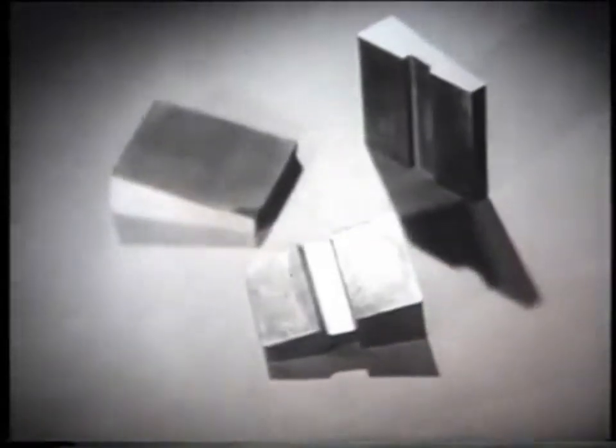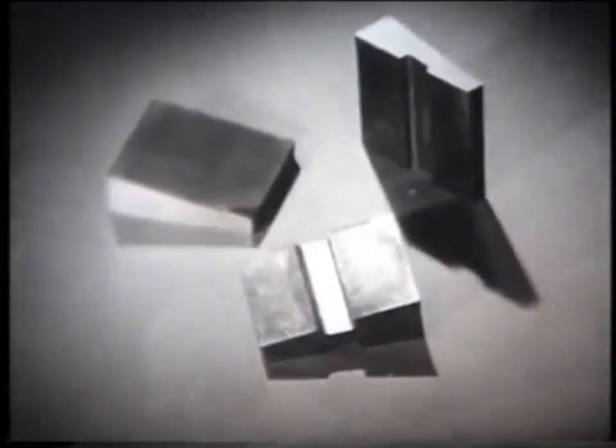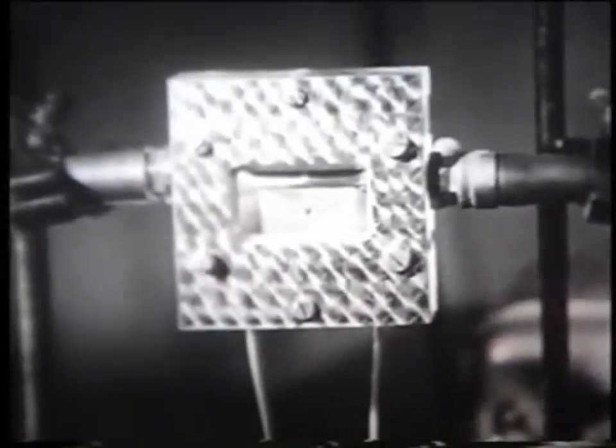These methods make it possible to achieve a metal removal capacity of 1,500, 1,800 cubic millimeters per minute per 1,000 amperes of operating current. The treated surface has a high purity class. Besides, there is no zone of thermal influence. A very important feature of electrochemical processing is that the dissolution rate does not depend on the mechanical properties of the part material.